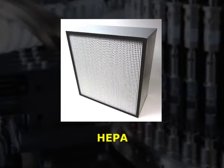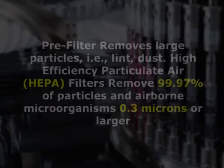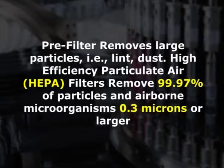HEPA provides a constant flow of air to the controlled area and the air is filtered. Laminar Airflow Workbench (LAFW) is designed to reduce the risk of airborne contamination during preparation of sterile products. Airflow control. Pre-filter removes the large particles, that is the lint, dust. High efficiency particulate air, the HEPA filters, remove 99.97% of particles and airborne microorganisms of 0.3 micron or larger.